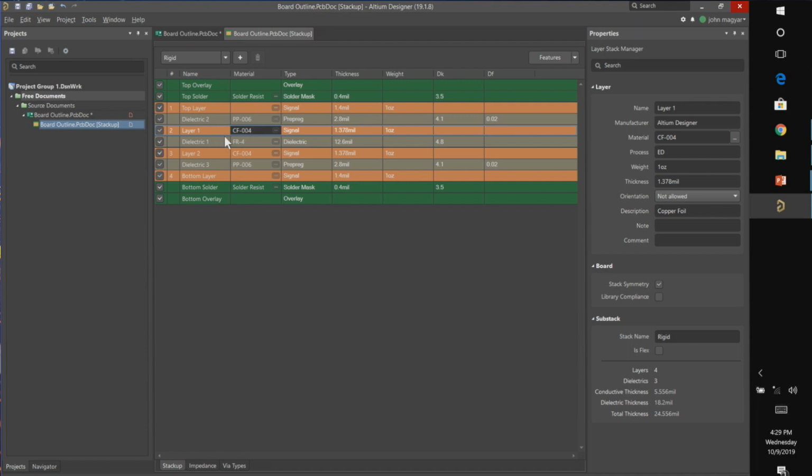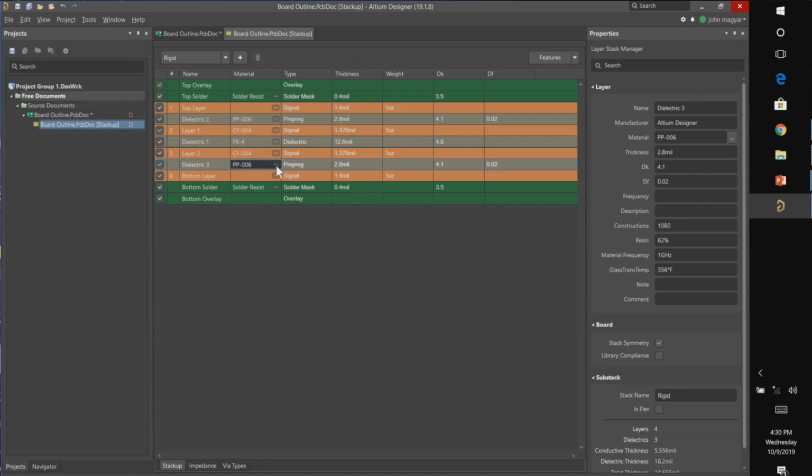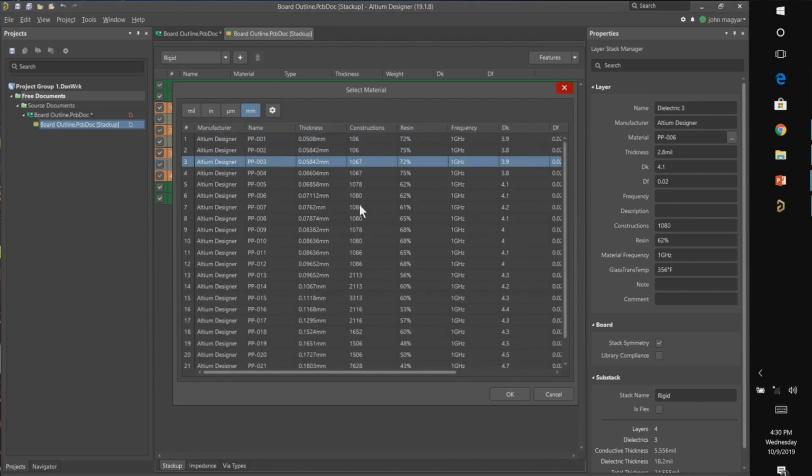But the dielectric for the bendable, it's usually like a Kapton type, but they're all selectable from this list. And if you work with your fabricator, they'll provide guidance on that. Some materials are one bend only and some are, well, they have different characteristics. If it's constant bending, you might use something more substantial versus a one-time bend to get it into place.